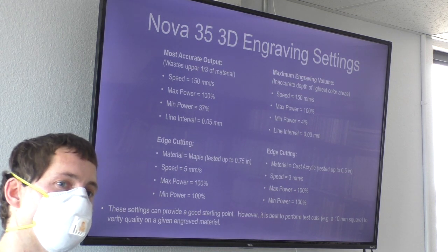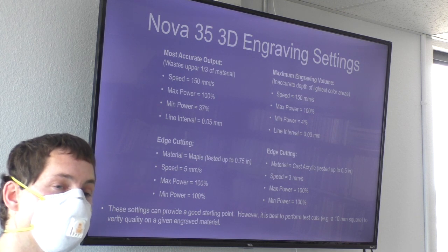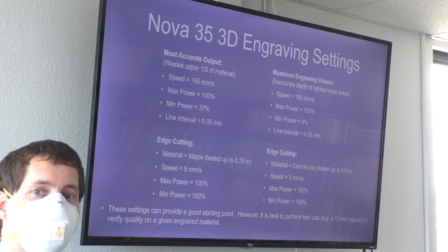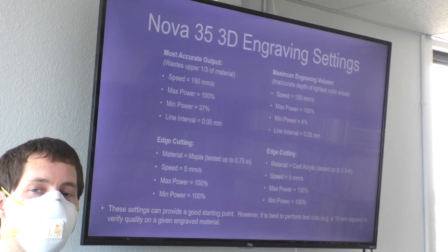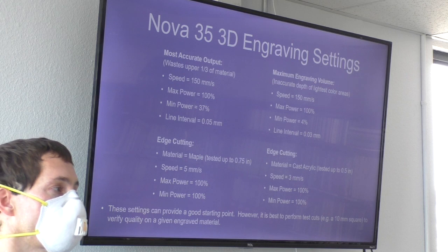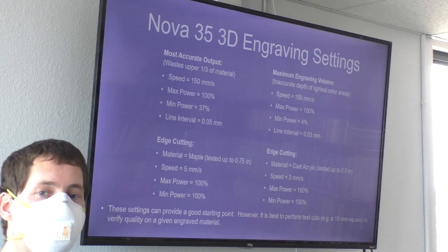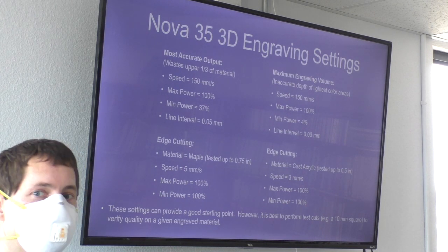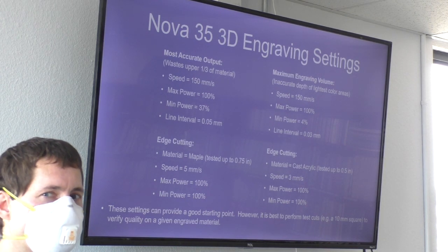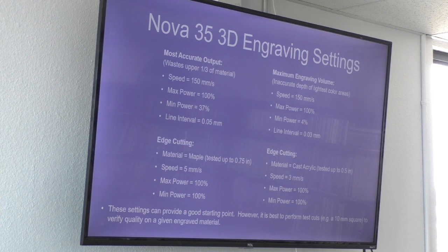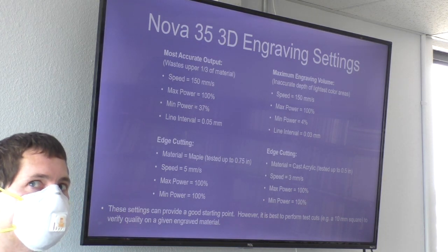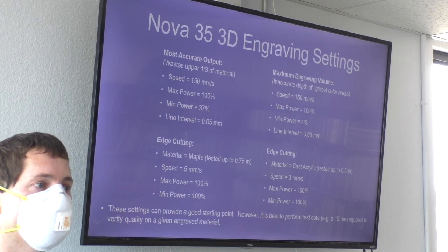Yeah, there is a fire detection system in the laser. Oh, there is? Oh, really? Yes, it is a metal plate that's under the gantry, if you take a look at it, and that would detect the heat of a flame and either turn the laser off or kill the machine. Cool. That's amazing. But don't let it get to that. Don't test it. I think if it's that high, you're already going to damage the machine. Yeah, because it's probably 5 inches-ish off the work surface is where that detection plate is.